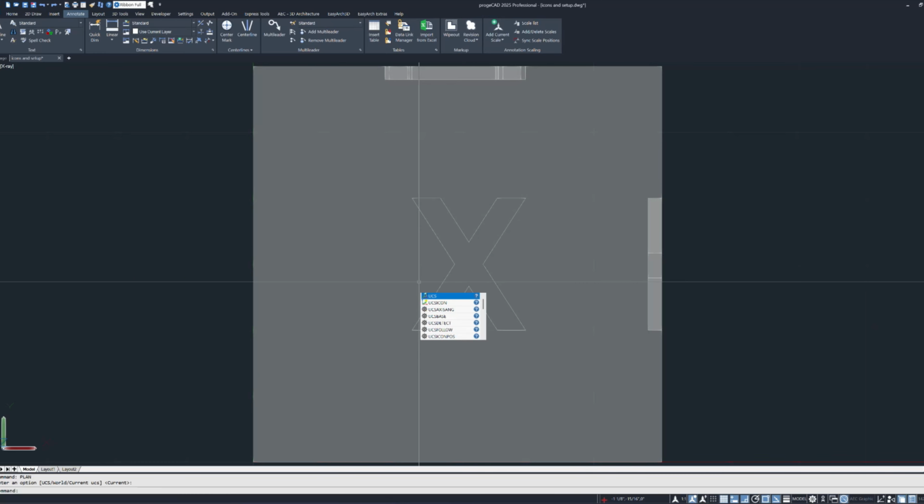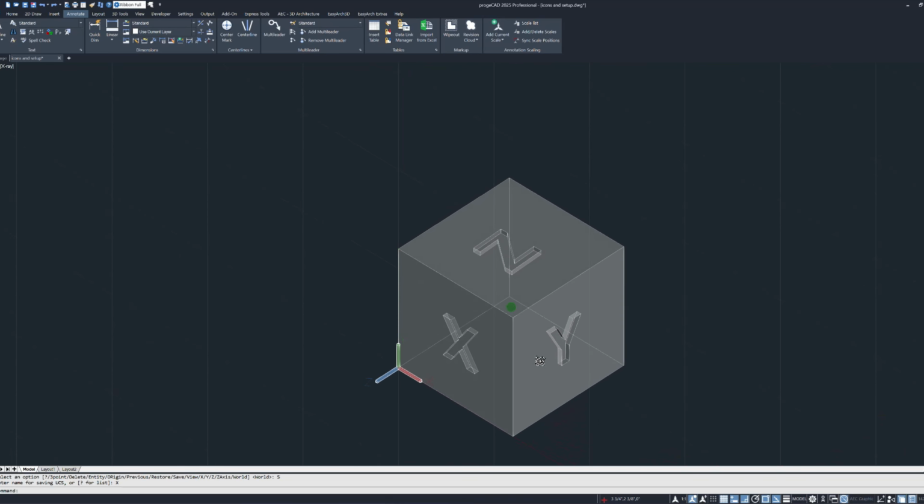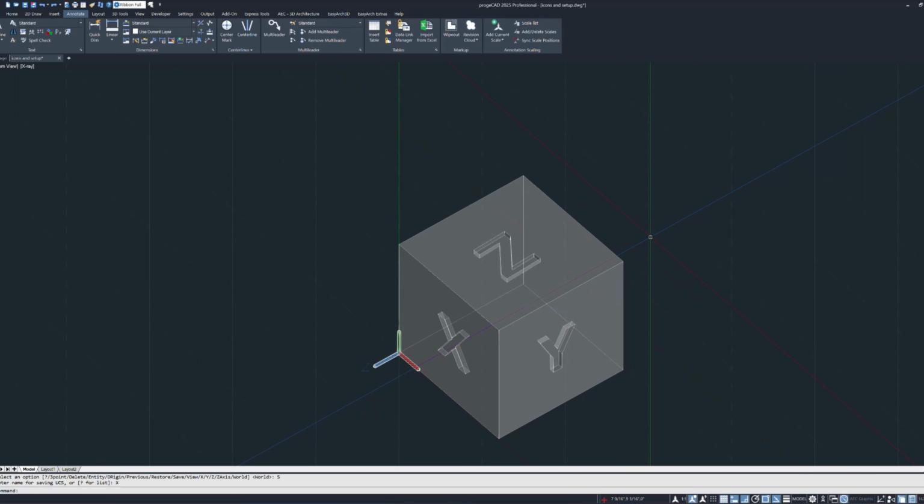Now enter a command called PLAN. This command will rotate our view to the coordinates we defined with the last UCS. It is important to save the view so we can recall it easily. I like to use one-letter views, which makes getting to the view quick without spending time typing, but sometimes it may be better to use longer names to be more recognizable. Use whatever name is comfortable to you. Do this name save before moving to the next step.